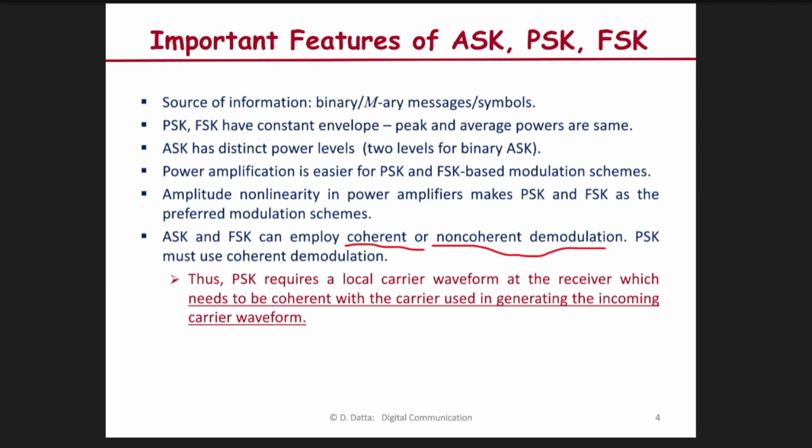Because in PSK the information lies in the phase, and the phase of the carrier should be tracked by the receiver. The moment you want to track the phase of the signal, not the amplitude or frequency, you have to be in phase with the signal if you want to know the phase. So PSK requires a local carrier waveform at the receiver, which needs to be coherent with the carrier used in generating the incoming carrier waveform.